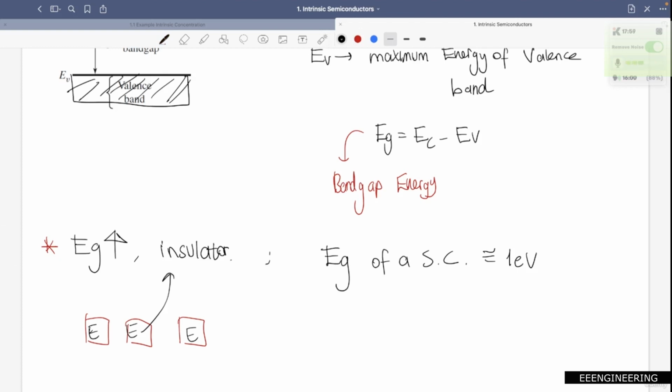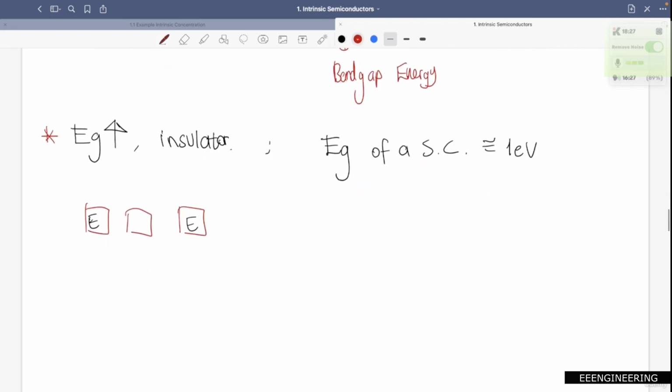So as our temperature increases, more electrons will break free and more empty states are created. And the neighbor electron of the empty space, for instance, if this one gains enough energy and leaves, then we will have an empty space in here, and the neighbor might actually move into the empty space. And it seems like a positive charge moving into empty space. So that positive charge is called a hole. I know this is a little bit weird idea, but it is actually a great one.